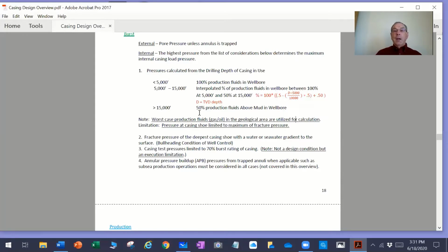But on the other hand, another way to look at this problem is if you end up with a well control event, number 2 would be the case. Say over the weekend you're trying to control this well, circulating it out on the choke, and you run out of barite. The boat is supposed to be bringing you barite to the rig, and the boat has a breakdown, or it gets a rope in the wheel and can't get to your location, or the weather's bad and you can't tie the boat up.